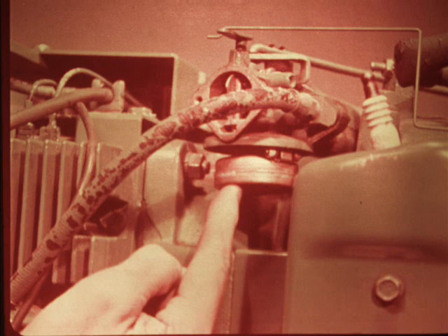Be sure the float is free and that the valve is not worn or clogged. If the float should stick in the up position, the valve will stay closed and the engine will suck the bowl dry. You should also check the ignition system, especially the points and timing.